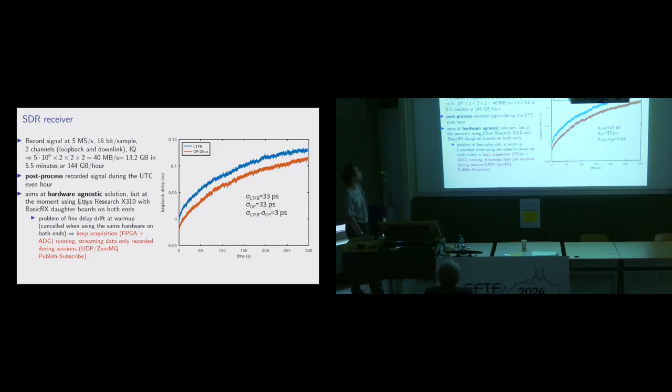And what we're doing here is we have these two X310s. And in the beginning, I was just doing the two-way time transfer. We had sub 200 picoseconds. I was super happy. And I didn't understand why the individual standard deviations were worse than the two-way time transfer standard deviation. How come that when you do the subtraction, you get a better standard deviation than the individual guys?